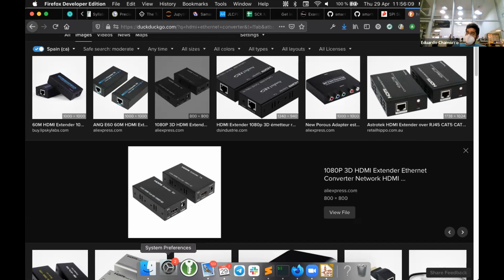For example, for this space, we have lots of sensors in the space. We will use RS485. It's really robust and I think can go up to 100 meters, or between 50 to 100 meters, depending on the cable quality. And it's super steady. The amount of data transmission is lower, but it also needs only 2 wires. It doesn't even share ground and voltage, just 2-line data.